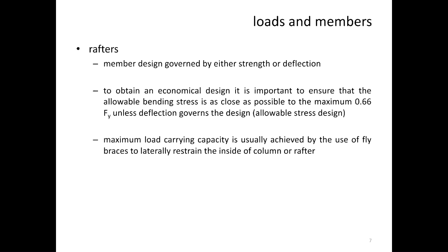Okay? So similarly for the rafters, they are governed by strength and deflection, which I've explained. We have to ensure that they satisfy strength. The strength means they can take the load. Serviceability means they can only deflect within certain limits without any yielding or failure of the member. So that's what strength and serviceability is. Okay?